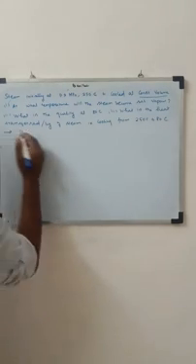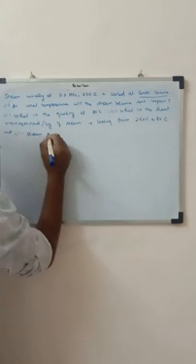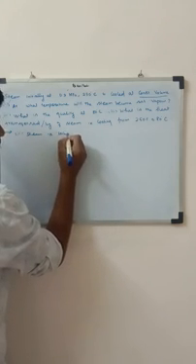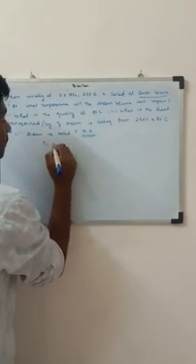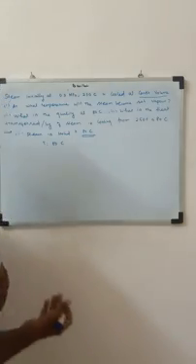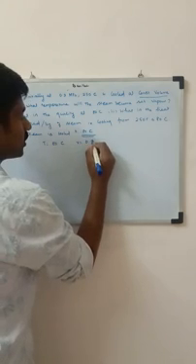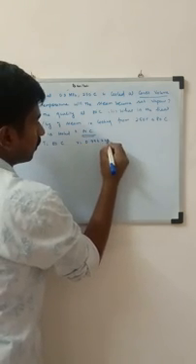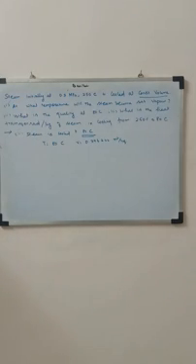For the second part, the steam is cooled to 80 degrees. My temperature is 80. And I also know another thing, which is the volume. Volume remains constant throughout the process. So my volume is 0.79644 meters cubed per kg. So these are the two things that I have now.